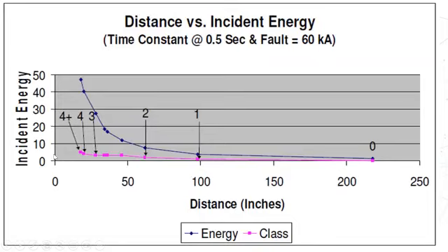So that's why there are different tricks being used. For example, if you need to verify the absence of voltage, use long handle testers at high voltage. The greater the distance you are able to create, the lesser the incident energy will be. If you go closer to the equipment or energized part, the incident energy will be higher. So in the exam, they are going to test your knowledge about this change in the working distance. This basically comes under the scope change.